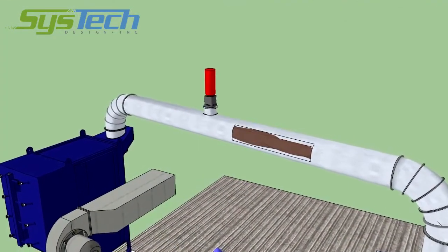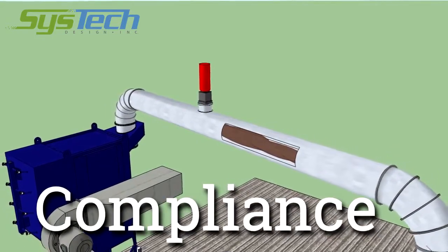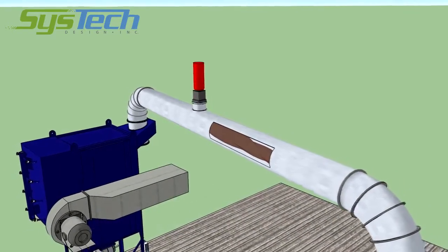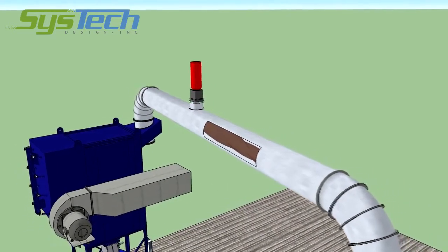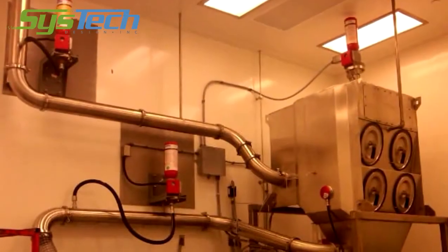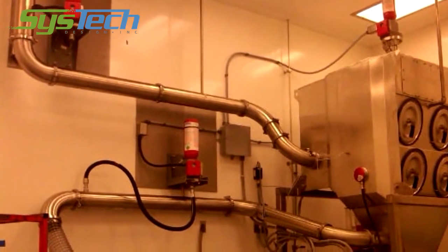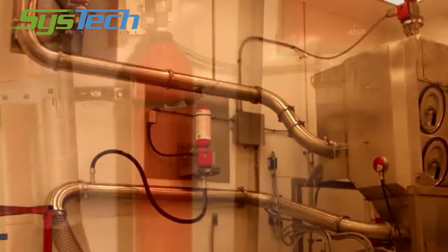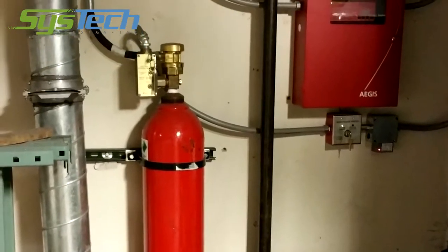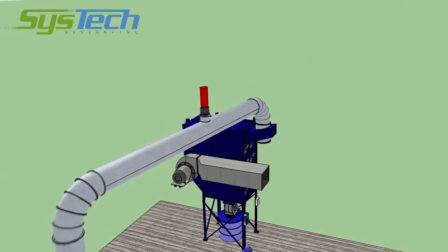Since we've published the 7 Cs, there has been a firestorm of activity around code compliance related to fire and explosion prevention and protection as dictated by NFPA and OSHA codes. Where fire is a potential issue, prevention and protection options include spark detection, extinguishing systems, use of abort gates, and CO2 systems. In addition, where combustible dust explosion is a concern, prevention and protection options might include explosion vents, chemical suppression systems, and isolation valves.